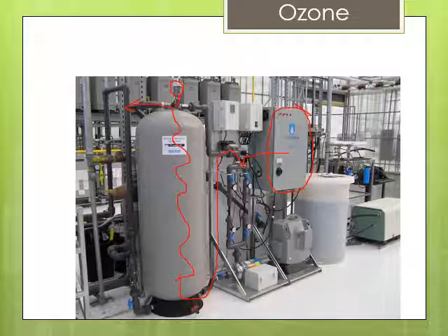So the bubbles will sort of rise, and as it fills, it burps out excess gas. Now, that's a really important part because ozone is dangerous for plants, and we want to make sure the ozone is dissolved in the water and not released in the greenhouse as a gas. So the system has to be working properly so you don't get ozone in your greenhouse.